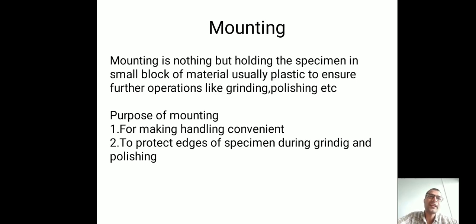Then, to protect the edges of the specimen during grinding and polishing, mounting protects the edges of the specimen, so that the internal microstructure will never undergo change while doing grinding and polishing.